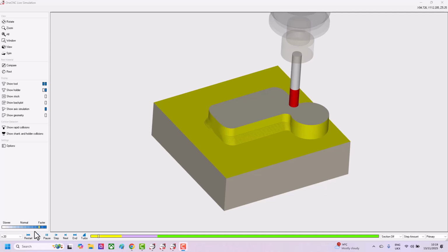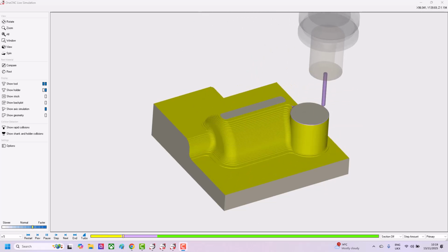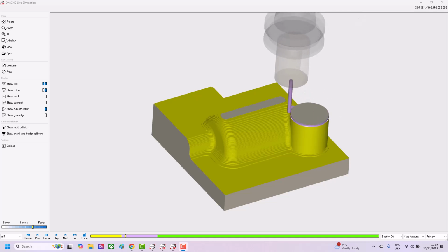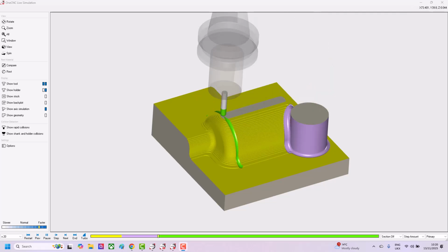And we'll just pause the video for a few seconds so you don't have to watch the Z level roughing. As I say, I did put a Z level finish down the chimney just so that my ball nose end mill didn't encroach it while machining. I'll just put this onto pause while it finishes that toolpath. So the chimney is about to finish, and there we go with our flow machining.